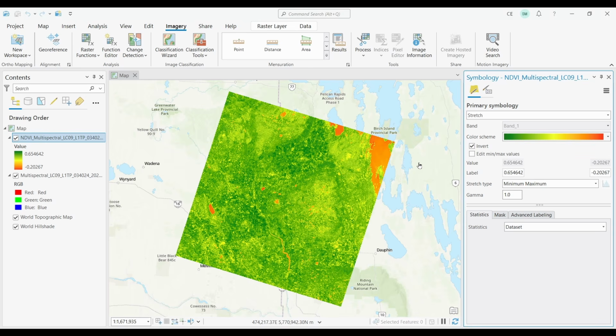urban areas. The last thing that I want to say is that there are just a couple of other things to keep in mind when you run this type of analysis. Depending on the imagery, you might have to pre-process the imagery to ensure that all bands are properly calibrated and aligned. This step may involve radiometric or geometric correction. Remember to consult with the ArcGIS Pro documentation or user guides for detailed instructions specific to the version you are using, as the interface and steps might vary slightly.